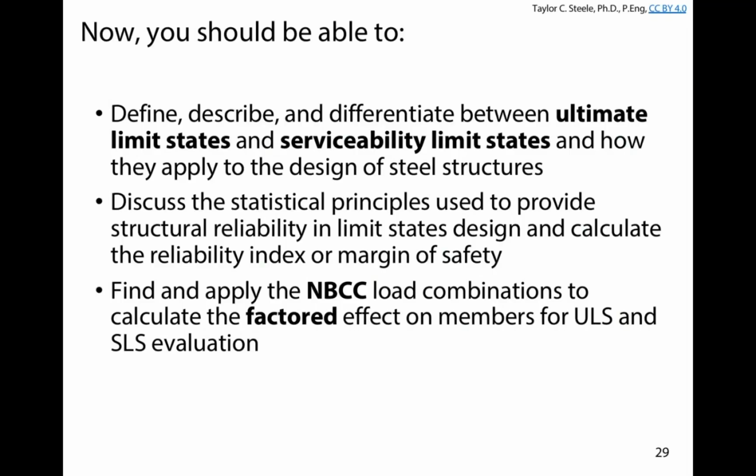To be able to discuss the statistical principles used to provide that structural reliability, think about things in terms of reliability index. Usually that's a value that we define based on an acceptable probability. And using that index, you should be able to calculate, for example, a margin of safety that would be acceptable based on the statistics of the load and resistance. And finally, you should be able to find and apply, most importantly, nothing is more important than this and this. What is ultimate limit states? Where are those factored load effects going to come from? And can you apply those load combinations to get that maximum factored effect acting on these structural members?